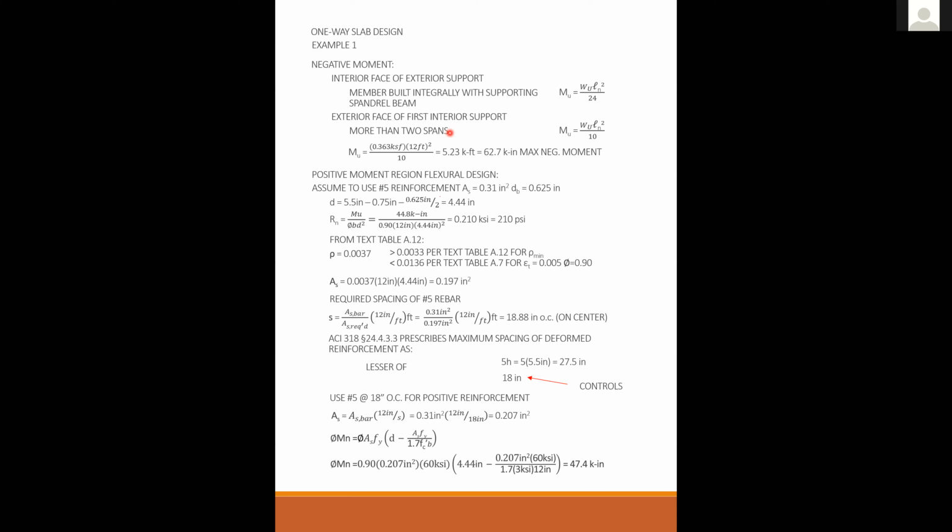Since the only thing that we're testing is a 12-inch width, does that mean there's a 12-inch width of the slab that doesn't have steel in it? No, it's not like that, because every time we're doing this design, we're really designing something that's 20, 30, 50 feet wide. So we're only taking a 12-inch wide strip for design so that everything is nice and easy.